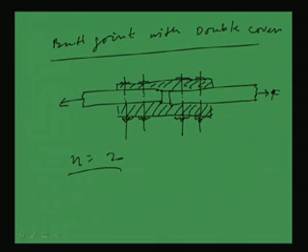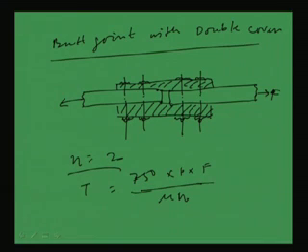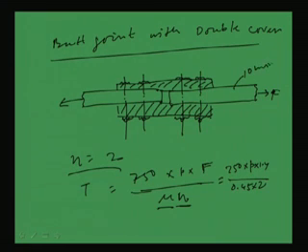So, if the number of interfaces is 2, then the equation T is equal to 750 into P into F by mu n, whatever we got in the earlier case. In this case this n is going to change. So this will become 750 into P into 1.4 by 0.45 into 2. So in this case T will become accordingly. Another thing is, let us assume this plate is also 10 mm and this plate also is 10 mm. In this way let us make it.